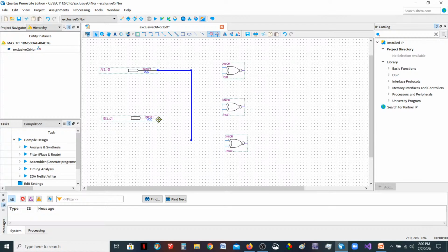There. See how it's much thicker. Okay, now as soon as you do this, you want to come back up here and click the orthogonal again. Otherwise, you're going to keep drawing buses everywhere. Okay, so I'm going to connect all of the first inputs to this string here. Whoops, Control-Z that. I don't like overshooting. I like clean wires. There we go.